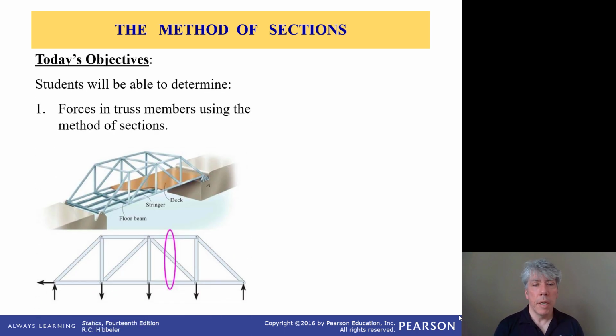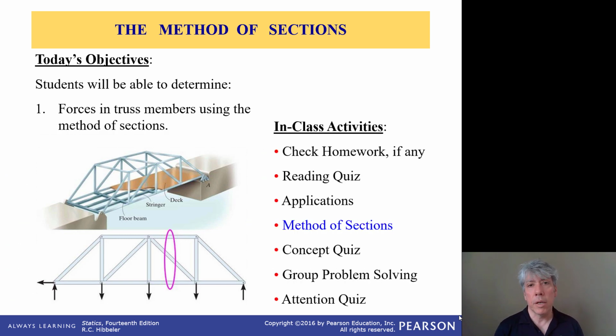Let's talk about the method of sections as applied to trusses. After this lecture, you should be able to determine the force in particular truss members using the method of sections. And it's a method that is superior in many cases to the method of joints, because while you could calculate the loads or the forces in all of the members, often you don't really need to. Often you just want the force in particular members, and this method of sections allows you to find those forces directly rather than having to step through the entire truss and all of the joints.